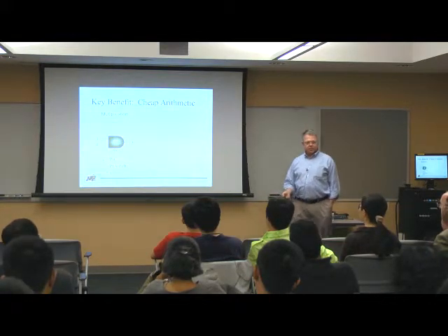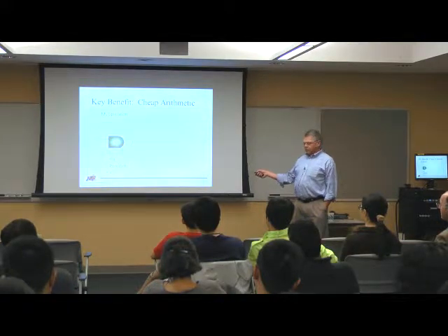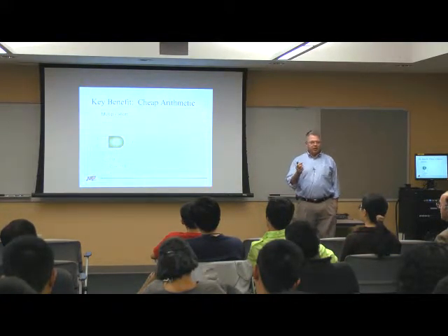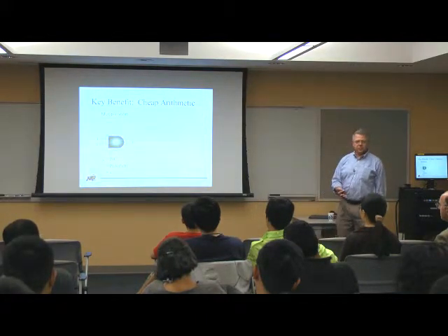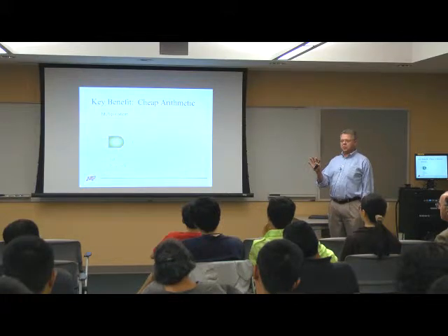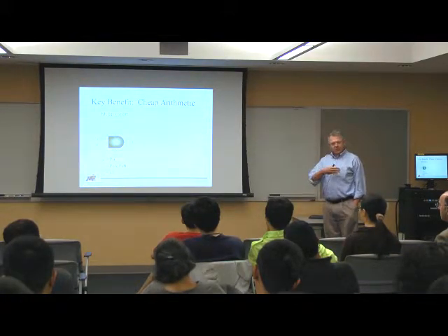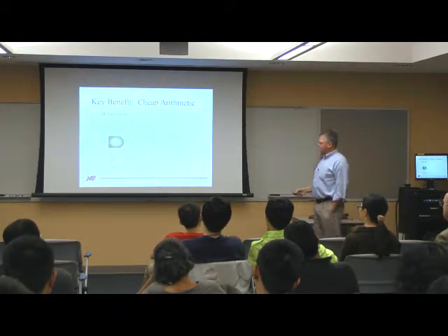If I just convert that to a mathematical description, then this C, fractional value, is just the product of A and B. So I've now got a multiplier made up of an AND gate. This is extremely inexpensive arithmetic. One AND gate to do a complete multiplication. I've paid for it in time because I've got these long streams of bits coming in, but it's very cheap to implement.